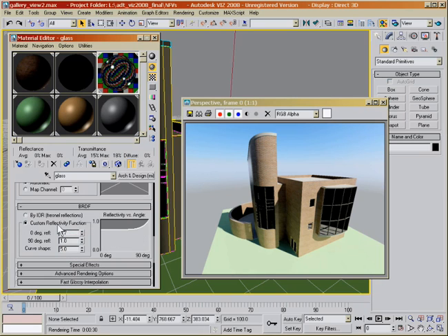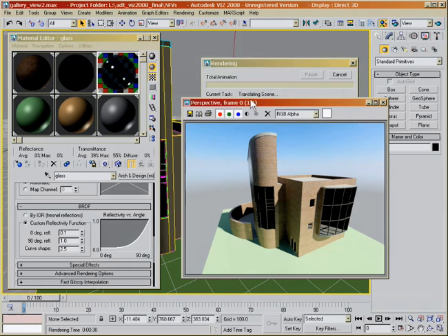For example, by using a low but not zero reflection at 0 degrees, something like 0.1, leaving 1 at 90 degrees and changing the curve to a smoother one, for example 2.5. And let's check how it renders with the settings so far.